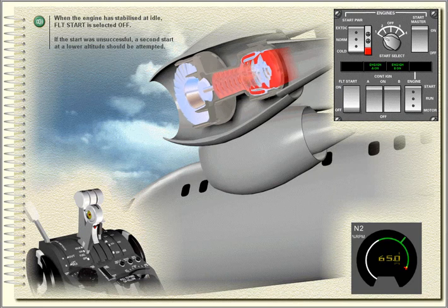When the engine has stabilized at idle, Flight Start is selected off. If the start was unsuccessful, a second start at a lower altitude should be attempted.